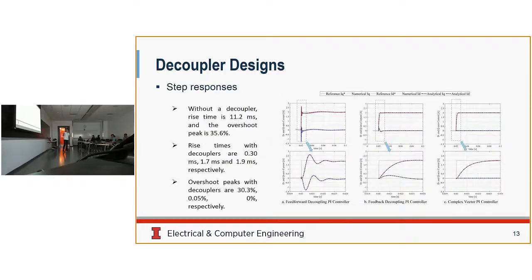And then through numerical simulations built in Simulink, we can see the effects. Without the decoupler, the rise time is 11 milliseconds, and the percentage overshoot is 35%.